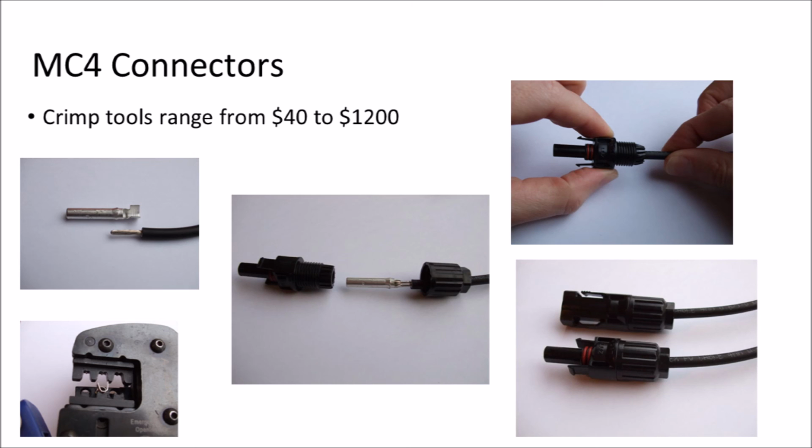Furthermore, the connector itself should not be exposed to any direct rain, such as dripping down in between the module frames or accumulating water. So attention must be paid with cable management and locating these connectors in addition to just making them. Finally, they click together with a nice snap.